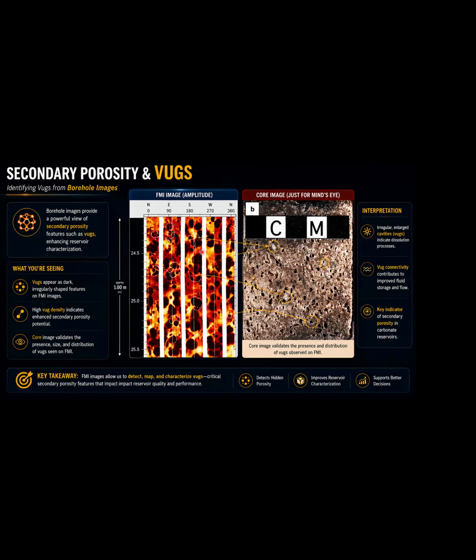All the dark appearance you see in the image, usually if it's open, which is the most dominant case, is the impact of the mud. Why? Because these holes or cavities are filled by the drilling mud, which in this case is usually water-based mud, which has a conductive nature.